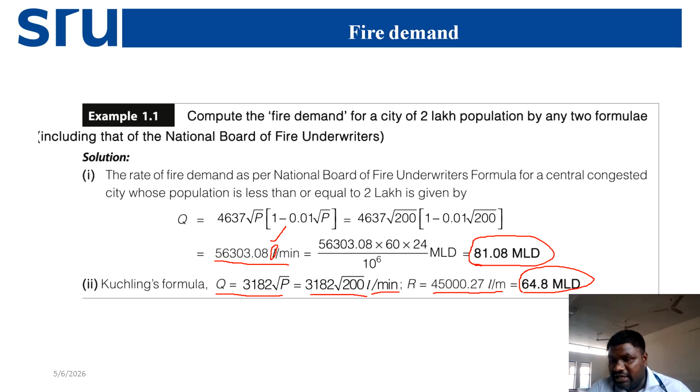Before designing distribution networks, we need to forecast the population, and as standards of living increase, the quantity also needs to increase. After forecasting the population, we multiply with the per capita water demand, and then multiply by some factors so that taps, losses, and everything are included.